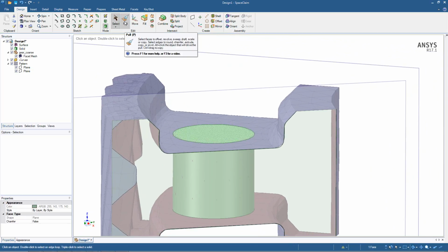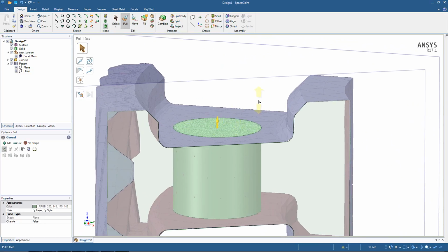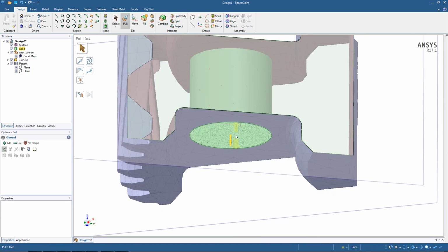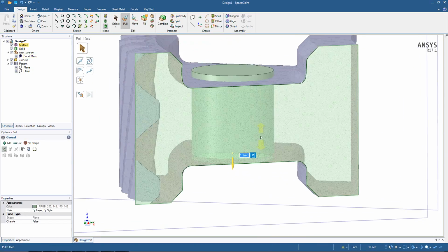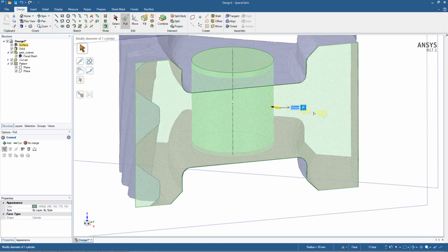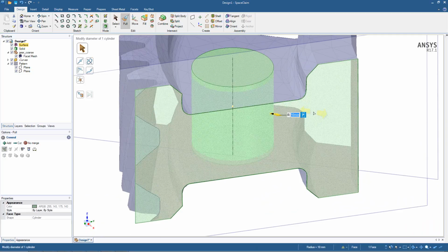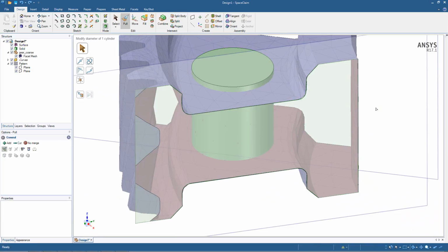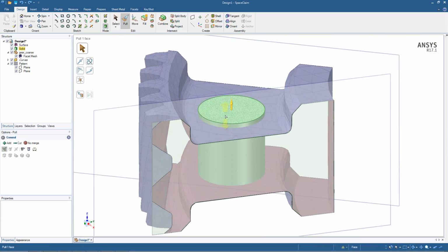And we can modify that by just simply using pull. And with the left mouse, I just drag in the white space and resize that to the size that I would like. Same thing down here, just pull that out. And if this diameter didn't happen to be the right size, you could just simply type in what you'd like it to be on the keyboard. Maybe that should be 9. So it's very easy to modify this type of geometry. Now we have that cylinder.